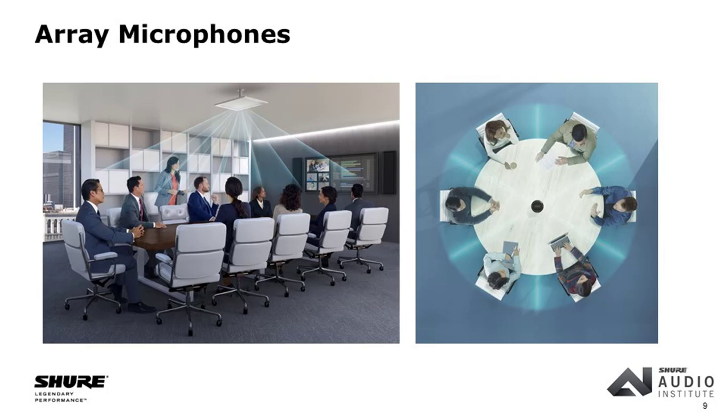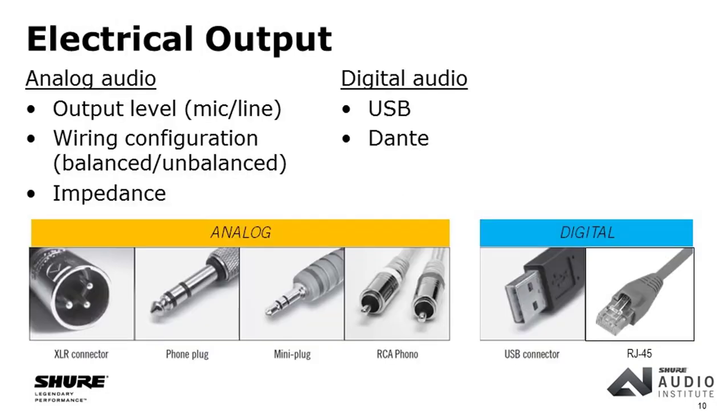A lot of what we end up talking about here, particularly in these AV conferencing applications, are condenser microphones. Right. Because they're more sensitive, which is needed since the microphone ends up being further away from the sound source, so you need that additional sensitivity. And condenser microphones can be made much smaller as well. So if you look at, especially, the ear-worn or lavalier mics or even the little gooseneck mics, they're very tiny, and that's something you can only really achieve and still have it sound good with a condenser microphone. But the concepts here could apply to dynamic or condenser.